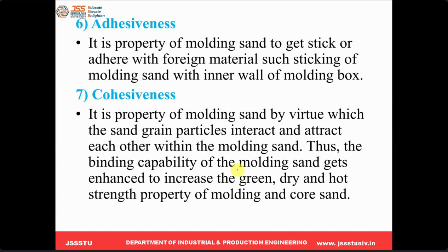See, there are two properties. Cohesive property. Where did you hear this? Cohesive and adhesive, you know these. Basically, cohesive and adhesive are used in fluid mechanics. Cohesive force is the molecular attraction force between the same fluids. Adhesive is between the liquid and the solid boundary.